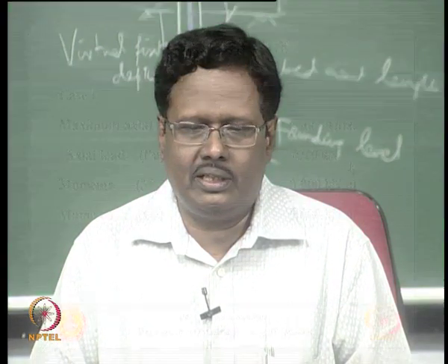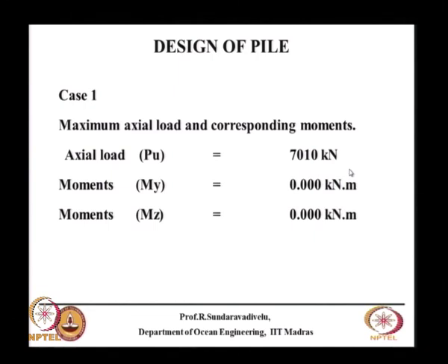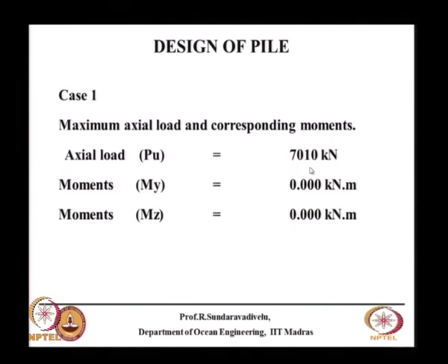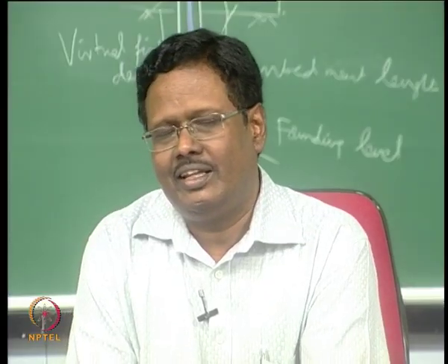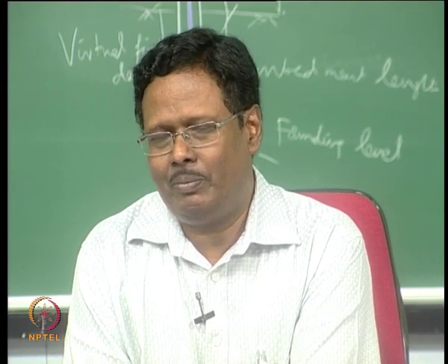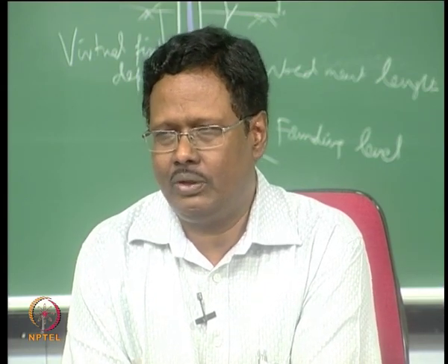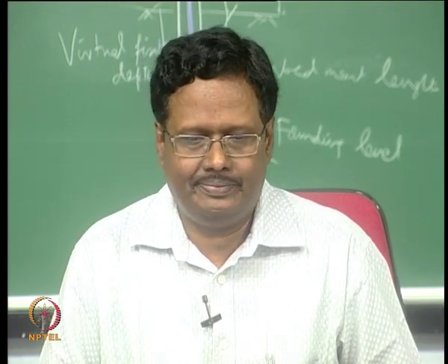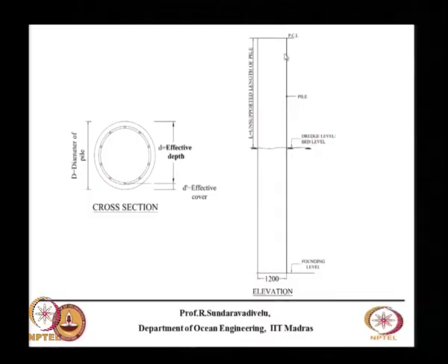Actually, we have to do this before construction of the facility. We do a test pile separately, apply the load and then see. I am recently designing one bridge for Indian Maritime University near Buckingham Canal. There we wanted about 500 ton capacity, but the pile load test gave only 450 tons capacity. So we are revising the number of piles before construction. The initial load test is very important.